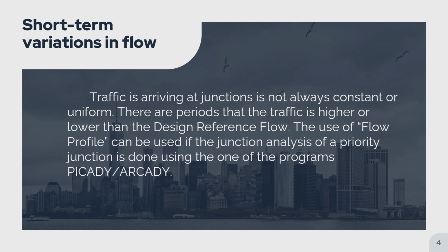If the junction analysis for a priority junction or roundabout is being done with the aid of one of the Transport Research Laboratory's computer programs, namely PICADY or ARCADY, such variations can be allowed for using a flow profile.